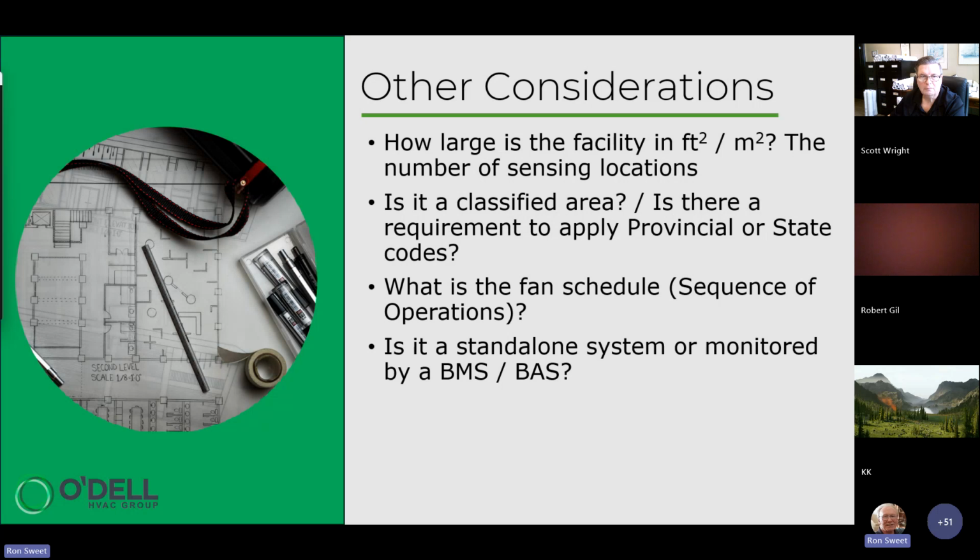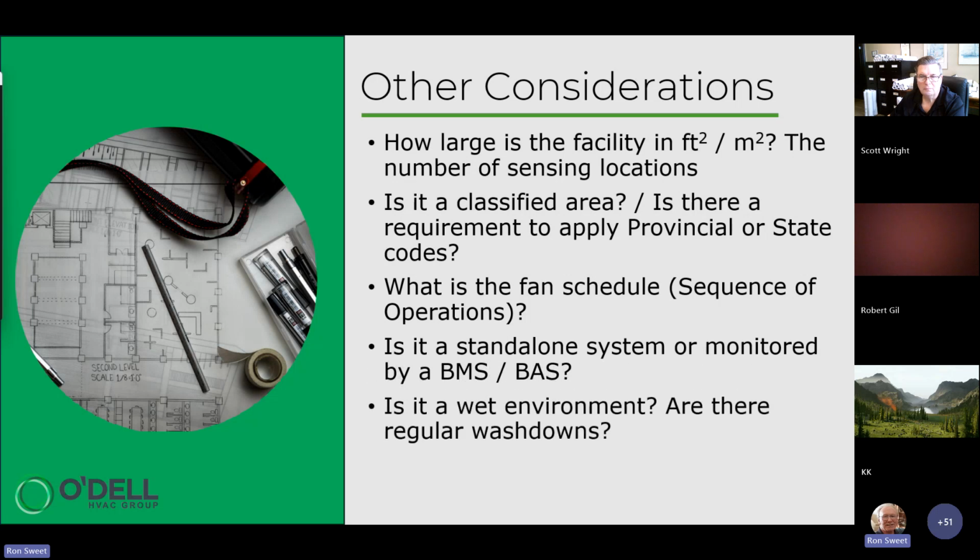But once the gas detection system or the other system that you want to interface to has been designed and is being installed, it's harder when you bring it up down the road. It's best to know right up front, right? And all the gas detection system manufacturers have some capability of providing that type of interface that you're going to be looking for. And then we have to take into account whether or not we're trying to install gas detection systems into a wet environment.